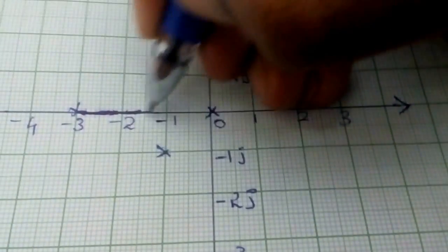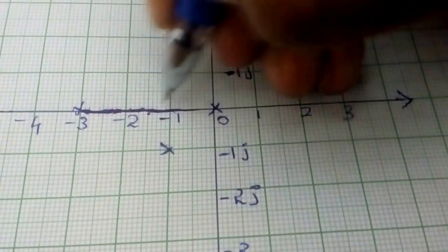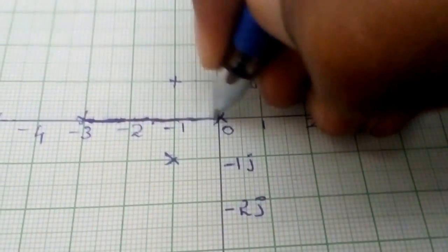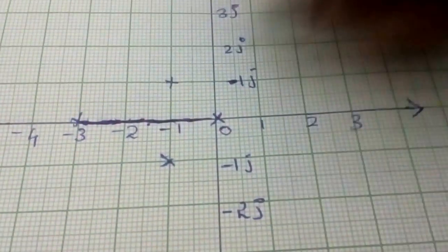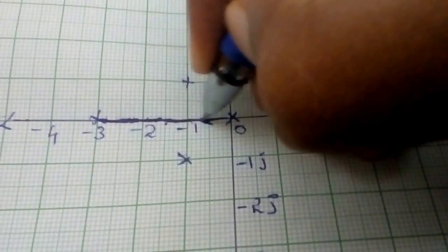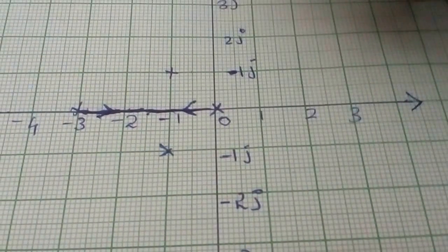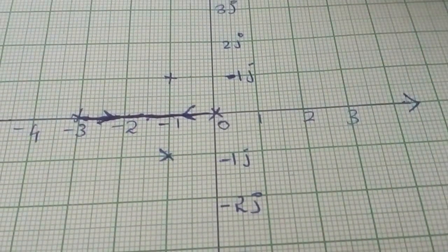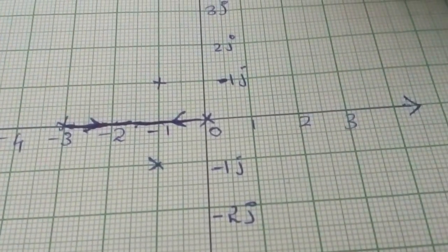So I'm darkening it to identify the part of the root locus. This section from 0 to -3 is part of the root locus. So the poles are moving in this way. The poles need to pair up with the zeros. Here the zeros will be at infinity, I mean minus infinity.